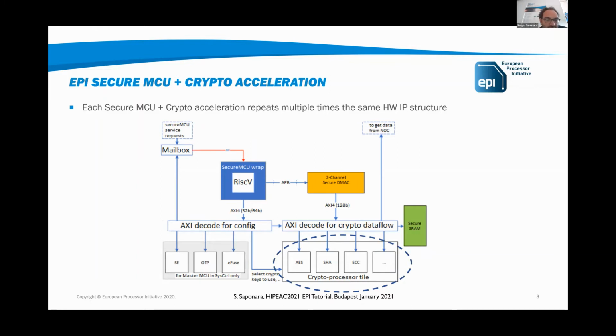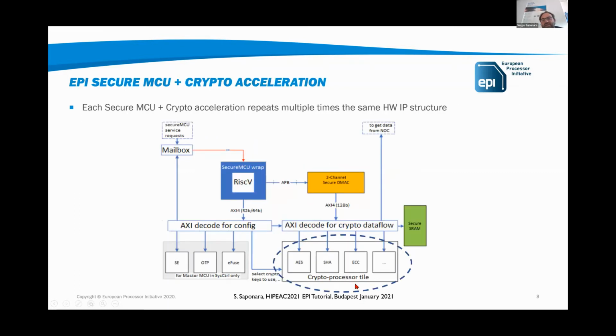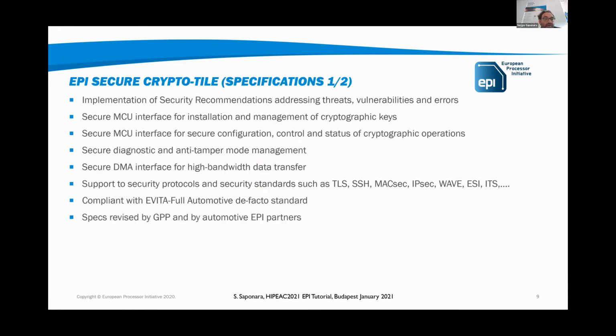Plus, specific to the security element, you can resynthesize for 7 nanometer, 6 nanometer, 5 nanometer, or FPGA. This is scalable RTL. Instead, these are technology dependent, like one-time programmable memory or fuses, needed for secure boot and also anti-tampering and this kind of stuff.